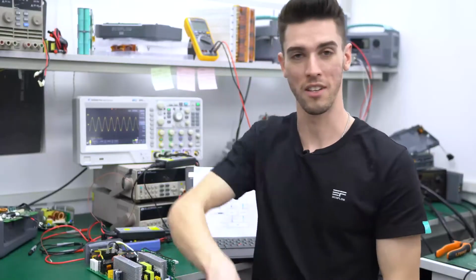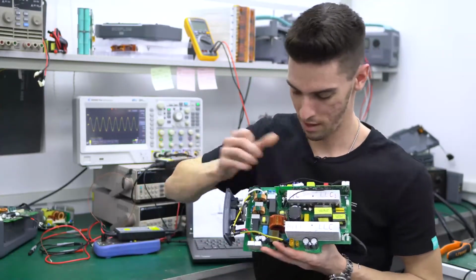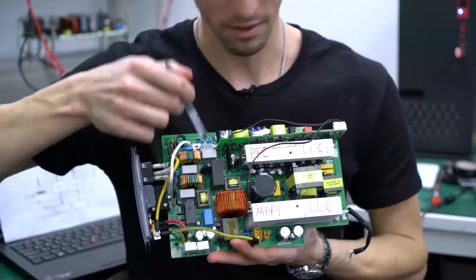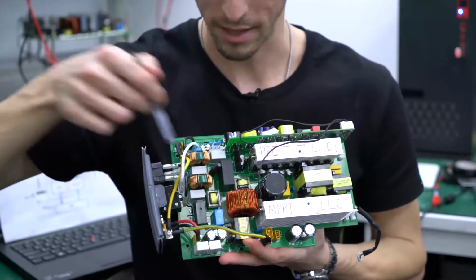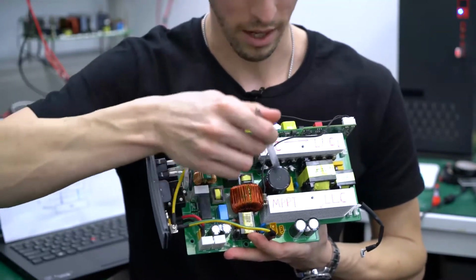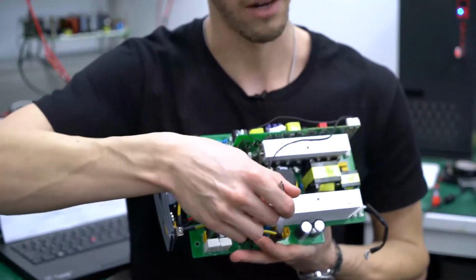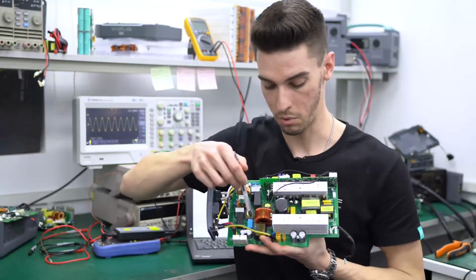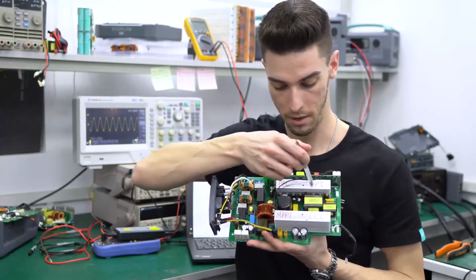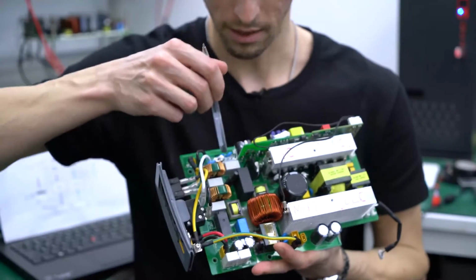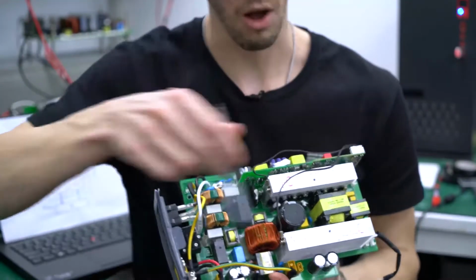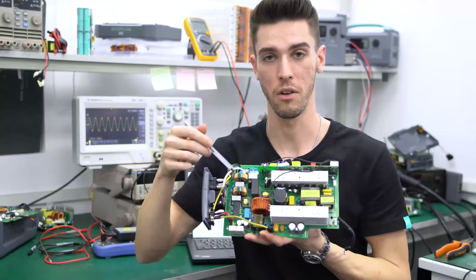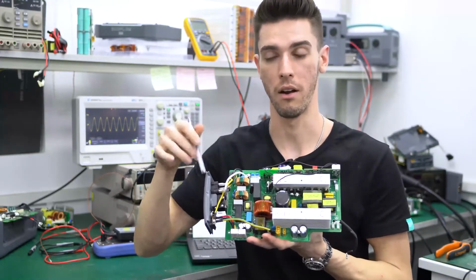All right, let's take a closer look at the EcoFlow inverter. Just like the chart, you have the AC input here. This is going to follow a path down to the bypass and directly out to the output. At the same time, it's also flowing this way down to this battery connector to charge the battery. If this connection is ever interrupted, the mode will change and the flow now goes this way to this relay and out to the output. This all happens within 30 milliseconds. So now that you've seen how we've configured our EcoFlow inverter, I want to talk a little bit more about our key features.